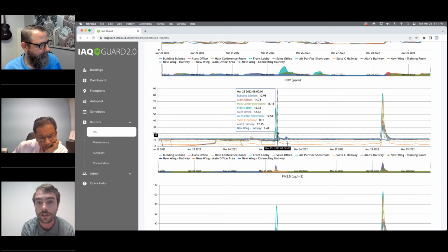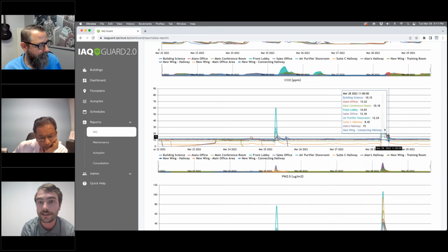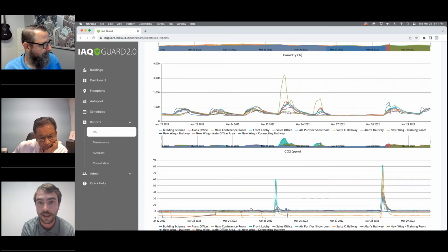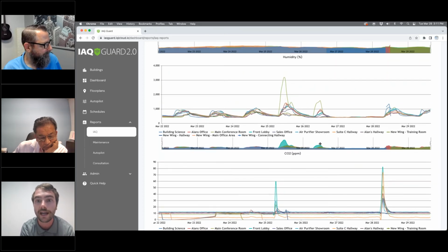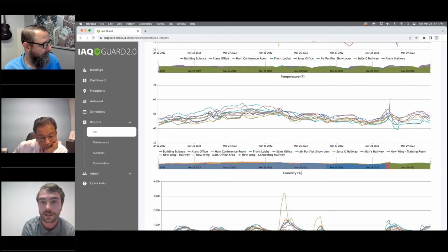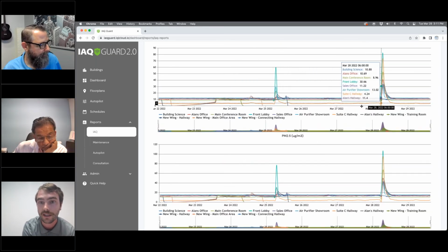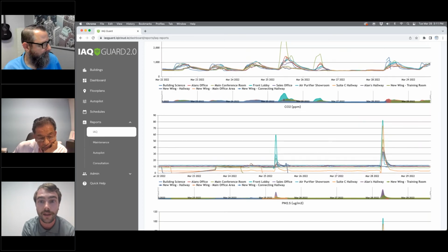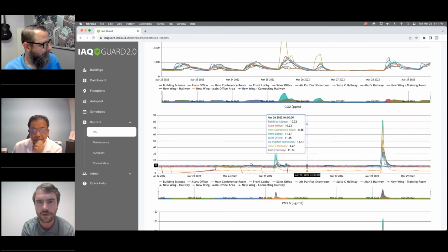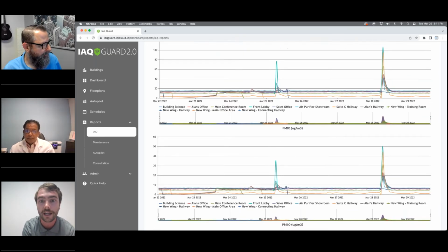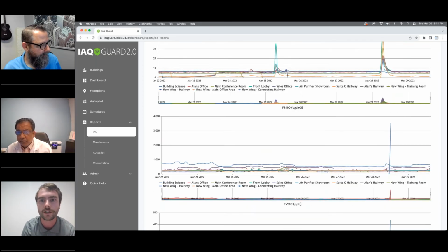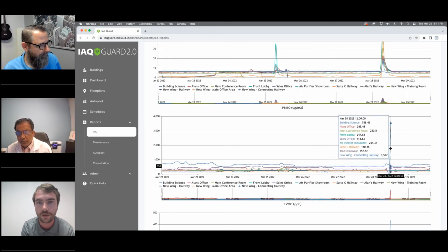And one way you can utilize this in the field is we've seen janitorial crews come through facilities, and we know exactly when they're using their vacuums, because oftentimes it kicks up a lot of the particulate matter in the room. Those monitors will pick up on those parameters that they're reading, and it can give you just a really good idea of actually what's going on in your building. Is there some work being done? Are there people in the room? What is being done to your facility?